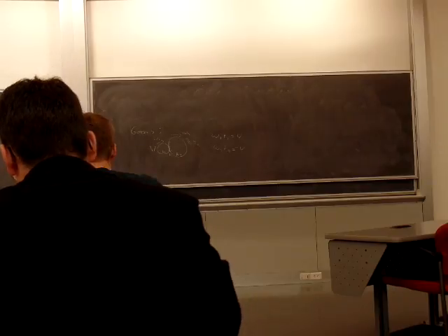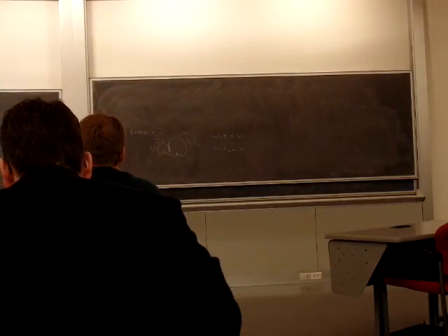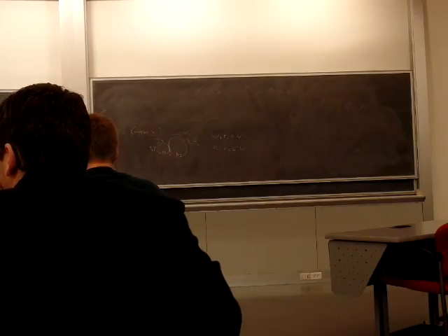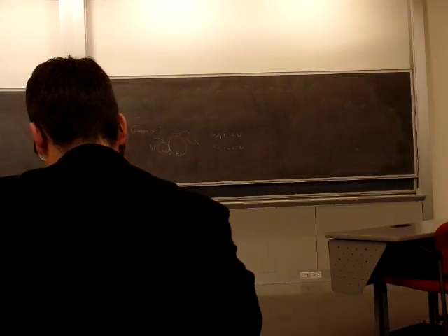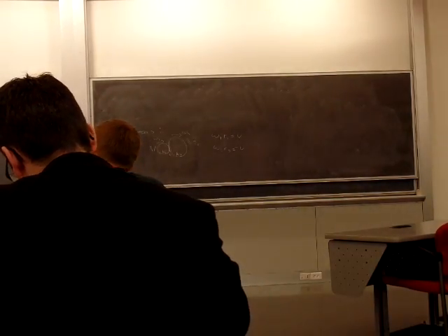In SI units, it's not diametral pitch, it is what? Module. It's module. Essentially the same type of thing. So instead of the number of teeth per unit diameter, it's the inverse of that. It's the tooth-to-tooth distance. They have to be the same. What we're saying is your teeth have to be the same size. All right.